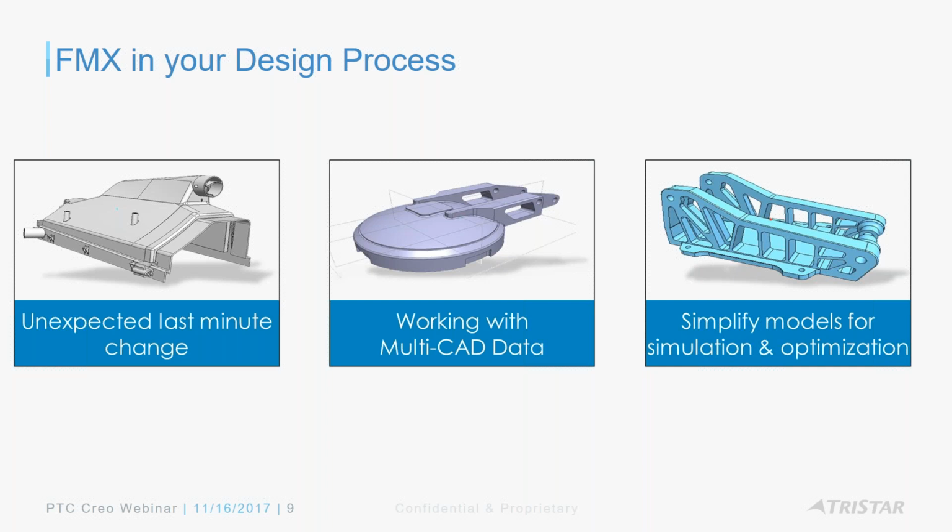But FMX is, again, very helpful here, where you're just saying, I want to remove this round. I want to remove these tiny holes. I want to remove these chamfers. That's going to unnecessarily increase my mesh size, for example. So it's also going to be very helpful on the simulation side for downstream use of your design. Not everybody requires the entire detail. They may want to get rid of some geometry rather than features. That's very helpful for that, FMX.